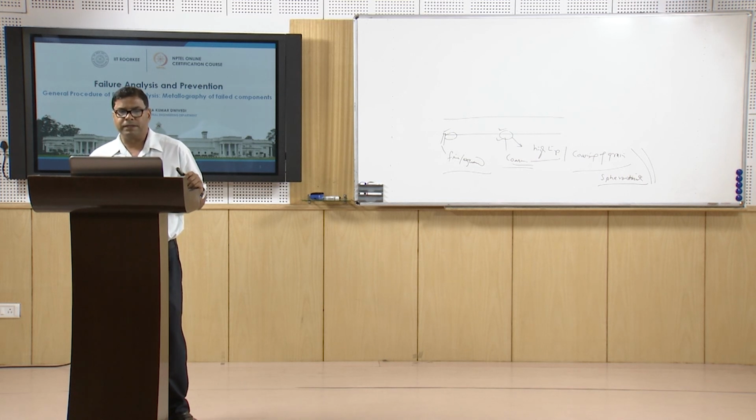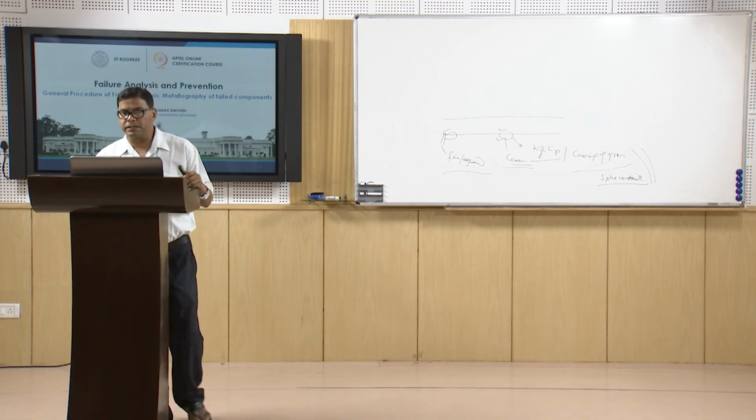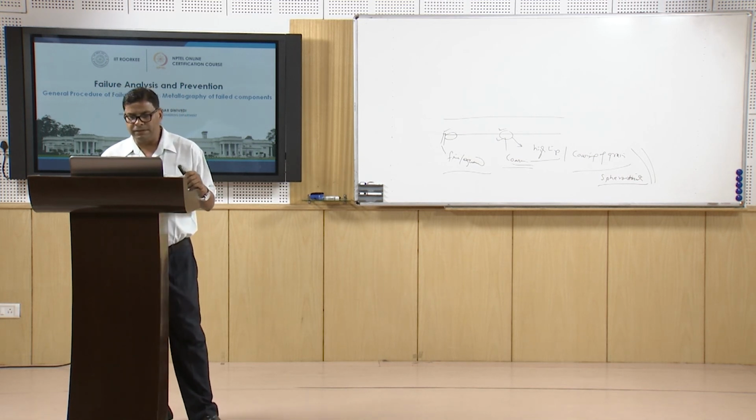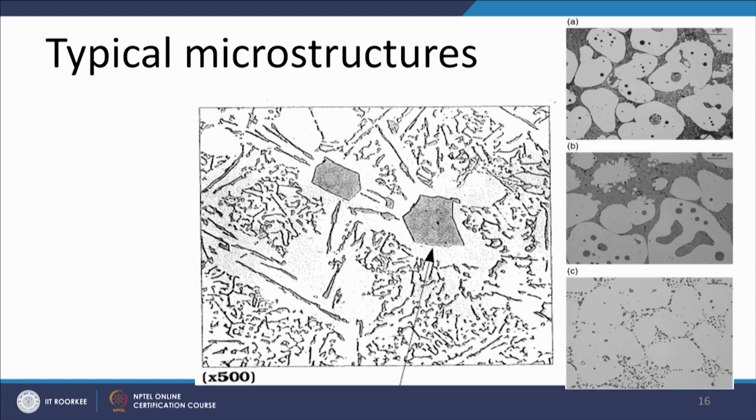Likewise, this is another aluminum silicon hypereutectic structure where coarse polyhedral shape particles are present along with the needle structures. So, such blocky particles as well as the needle shape constituents facilitate easy nucleation and growth of crack. If these are present, they may provide an easy site for the nucleation and growth of crack.